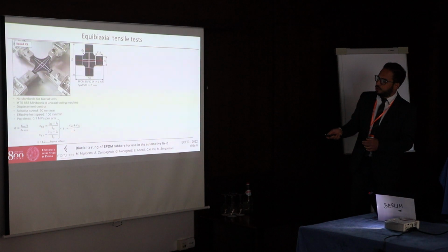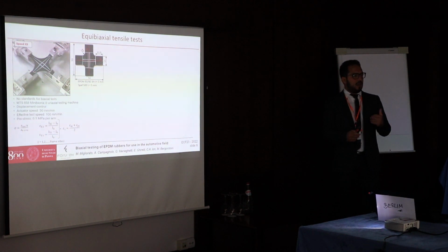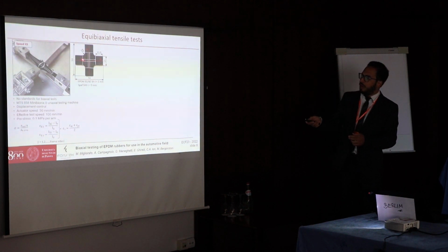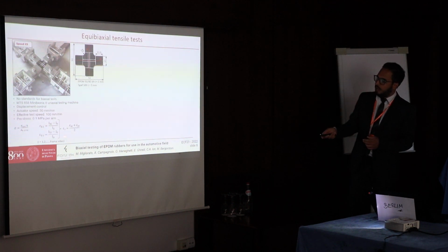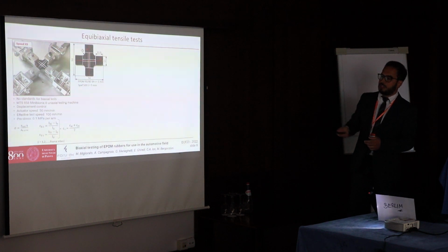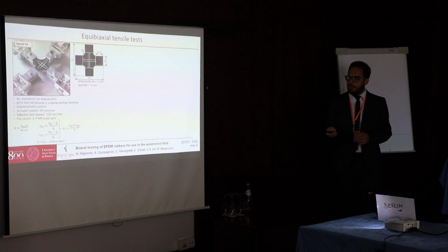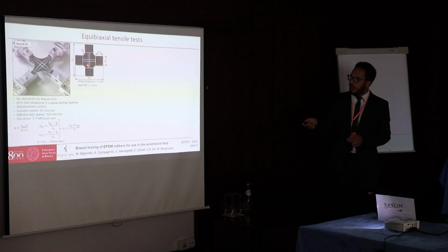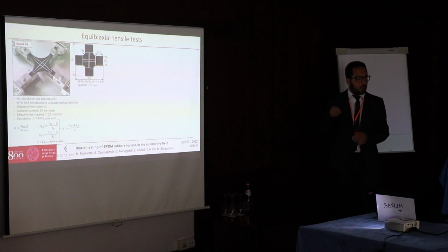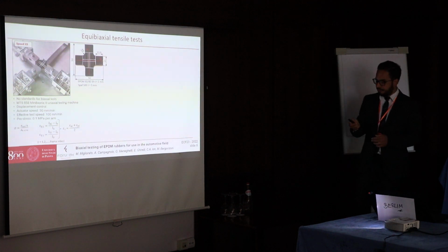While for the strain value, having the displacements of the reference markers over time, we have calculated the strain in the center of the specimen as the average between the strains acting along the x and y direction, assuming a uniform strain field within the reference square.